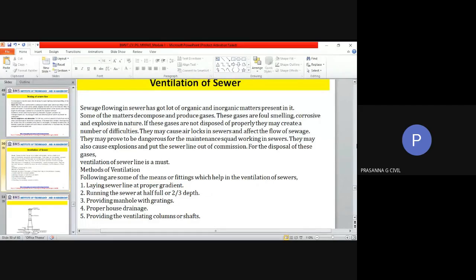Now, in your buildings or houses itself, you know that from the closets and all, we have a long pipe, a vent pipe that comes with a cowl at the top, which allows for fresh air to be within your system or chamber or toilet, whatever it is. So if that air is not removed, then those foul gases plus the ignitable gases will remain there. So the process for ventilation is to allow the fresh air to come into the system and the foul air